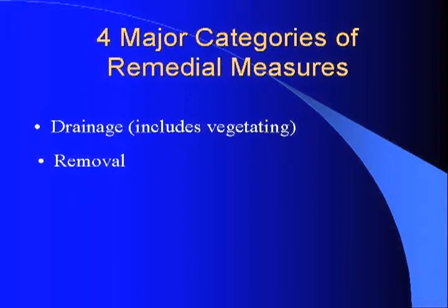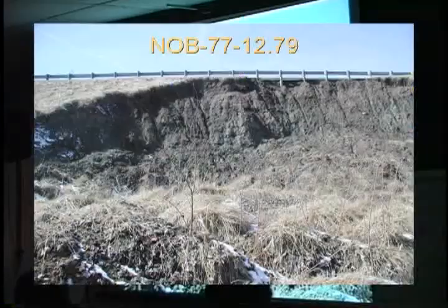Second most popular method of remedial measure is removal. Pretty straightforward. We're cutting out the failed material, in most cases trying to bench into a foundation soil or rock that is not failed, that's stronger, and then rebuilding it so that we're reinforcing it.